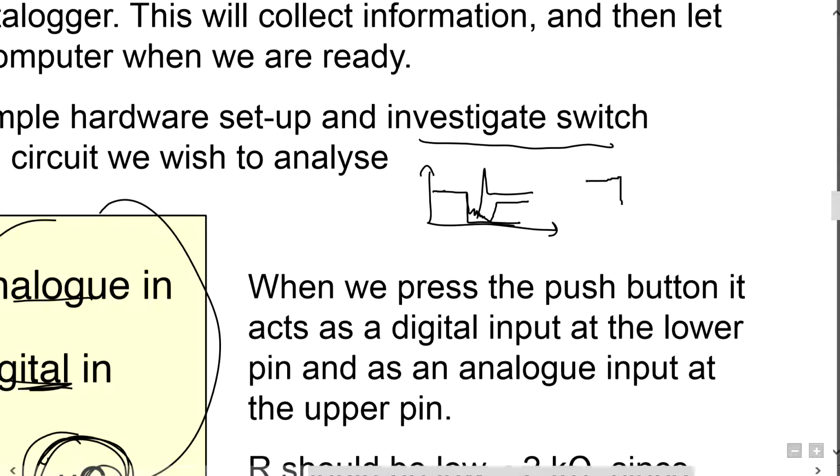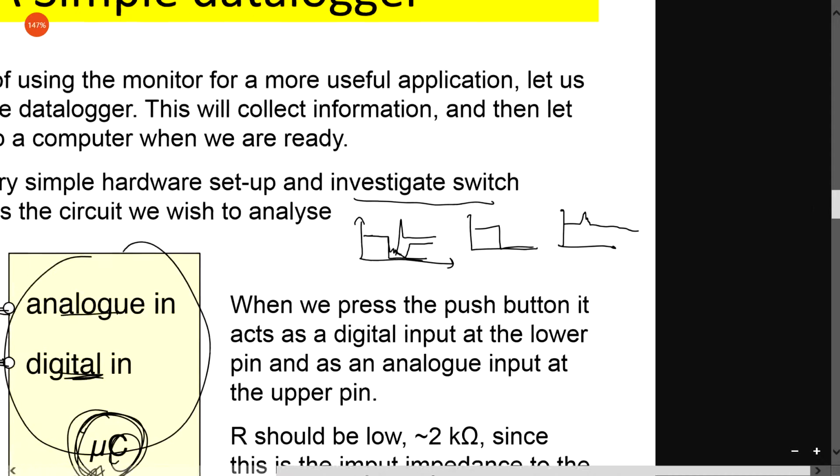So you want it to be like this, correct, but sometimes the spike itself is higher than your button, such that it thinks that you continue to press high. Alright, so that's the problem with the bounce switch.